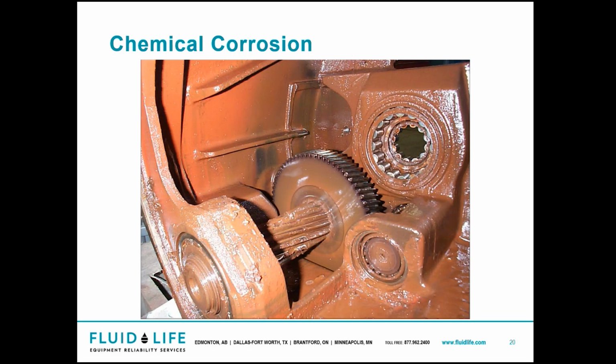Adding additives, bad idea. For example, an EP additive will actually have a huge effect on the rust and corrosion inhibitors, like you would see in this here. Rust and corrosion inhibitors obviously not necessarily doing their job there.